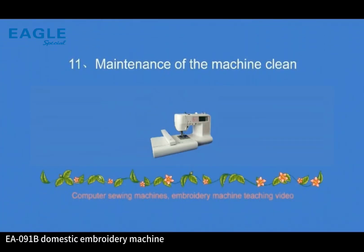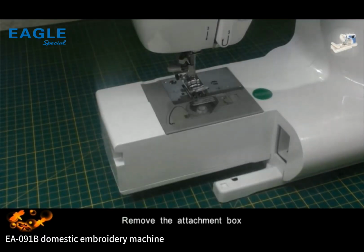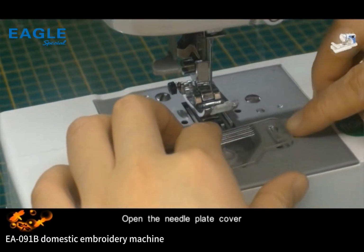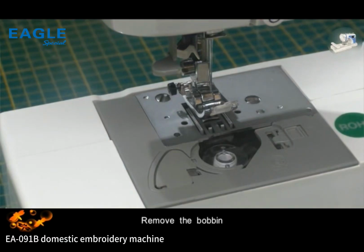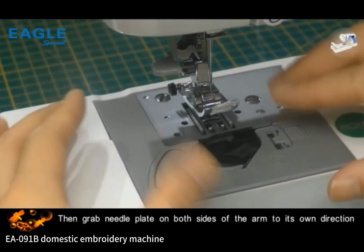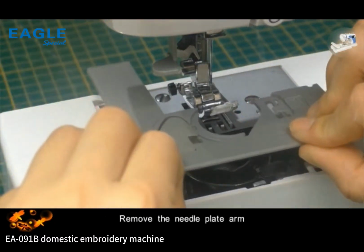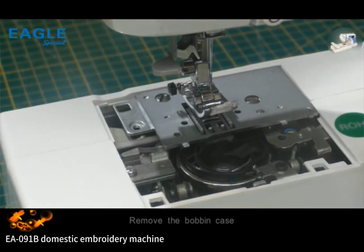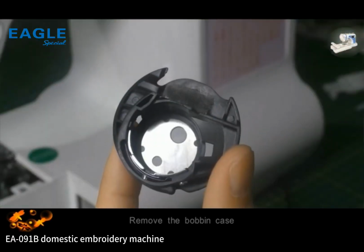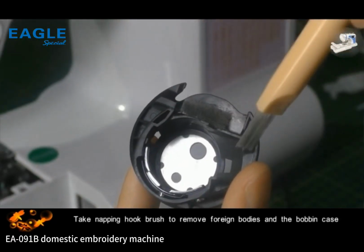11. Maintenance and cleaning of the machine. Shut off the power. Remove the attachment box. Open the needle plate cover. Remove the bobbin. Then grab the needle plate on both sides of the arm and pull it toward yourself. Remove the needle plate arm. Remove the bobbin case. Take the hook brush to remove foreign bodies from the bobbin case.